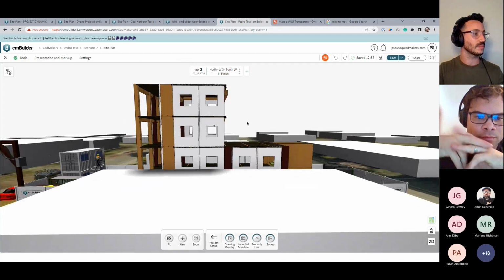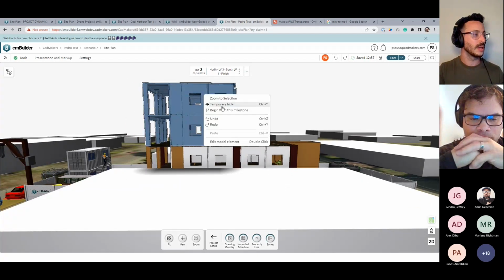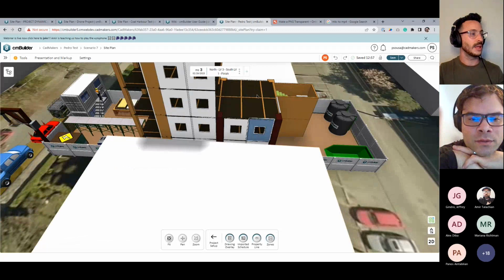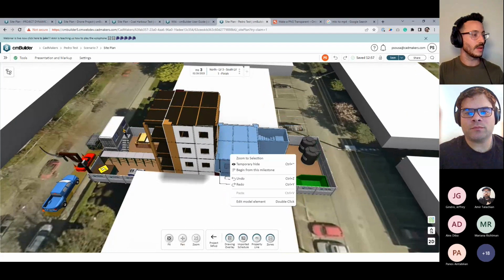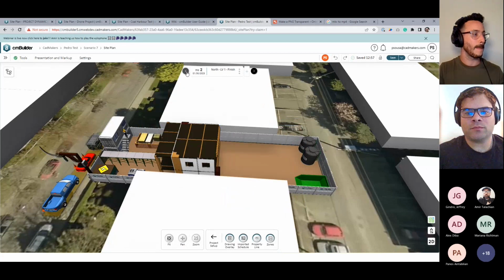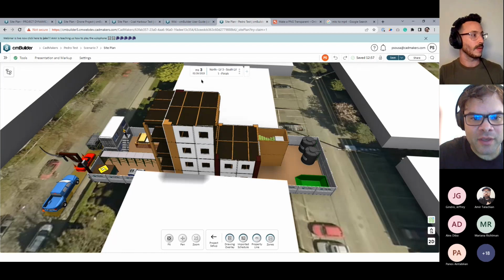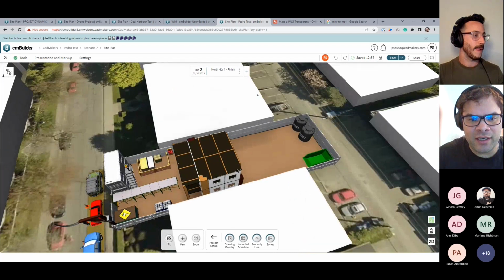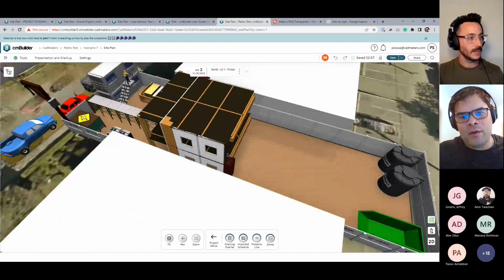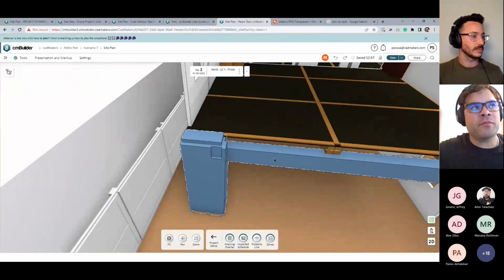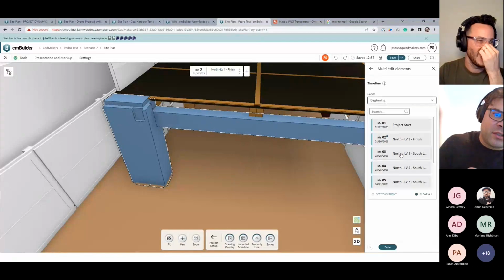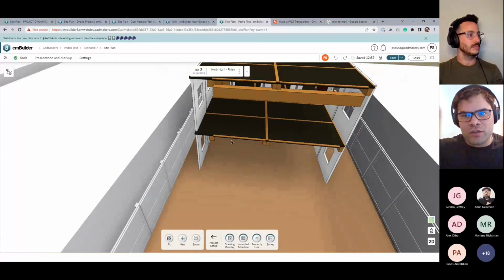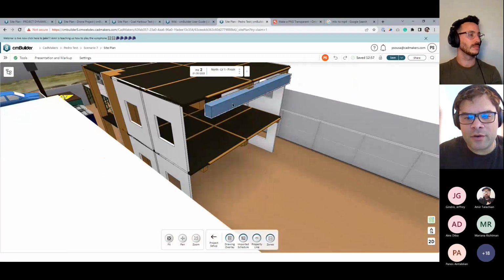Cool. So if I do this quickly over here, and then I do this part over here. One thing as Pedro's doing that, you might notice the lasso select will select the first item of its type. So if the first thing you hit is the model and then you drag it, it won't pick the resources in surrounding buildings. Just keep that in mind. Whereas if you hit the buildings or the resources first, it'll select all of those other elements in that category, in that type.